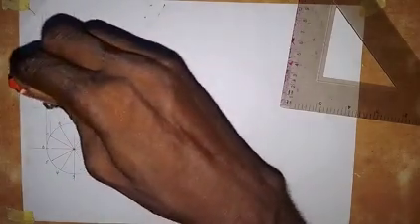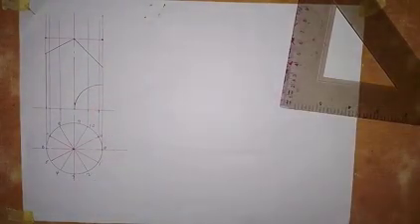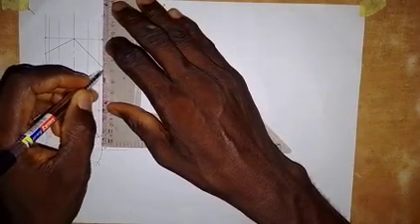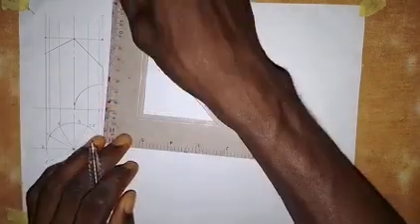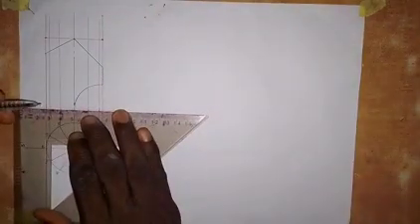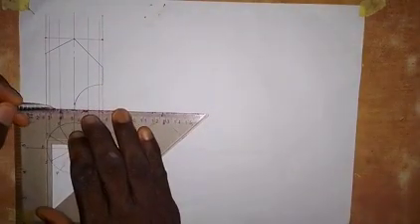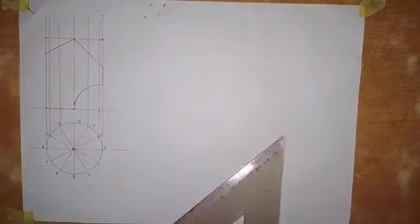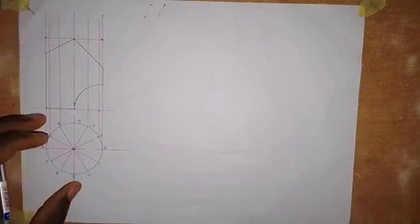Alright, so the given view has come out as we are instructed. What we need to do now is to make this line a thick line, and then we also make this line a thick line. Alright, so we have drawn the given view, and we have drawn the plan, though we are not asked to draw the plan, but we cannot draw the front elevation without constructing the plan. So please take note of that.